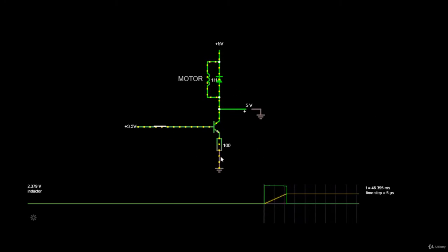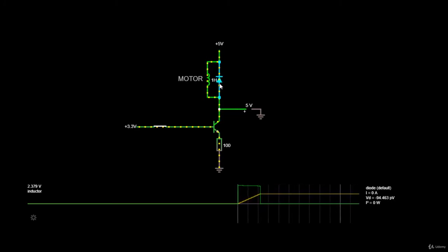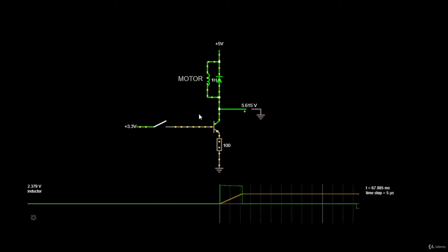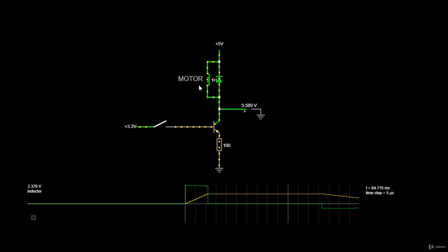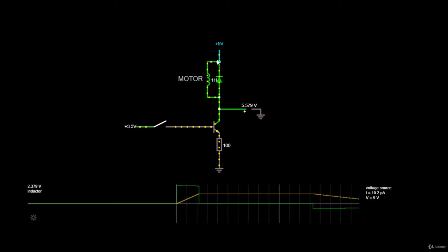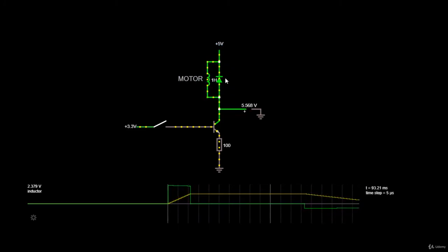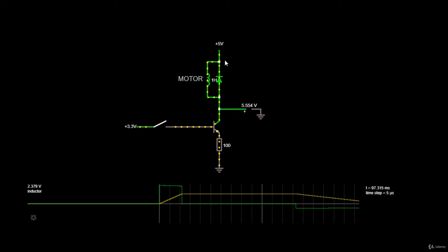Now let's try to repeat what we just did, but this time with the flyback diode back in its position. As you will see this time, when I turn off the motor, the flyback diode placed across the inductive load will give that negative voltage signal a safe path to discharge, actually looping over and over through the inductor and the diode until it eventually dies out.